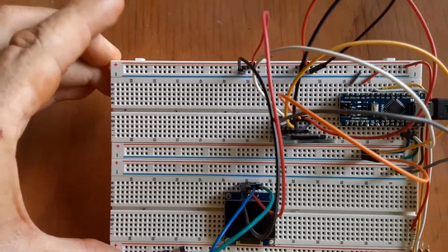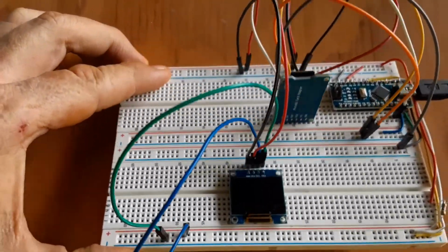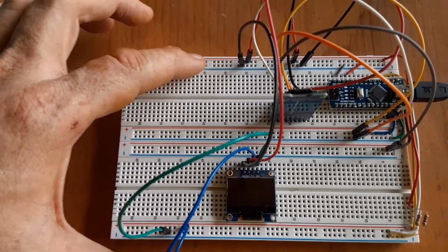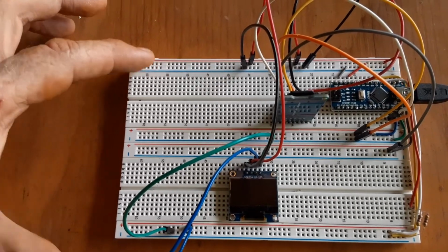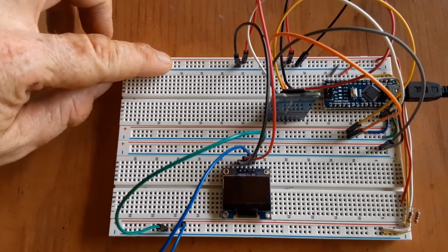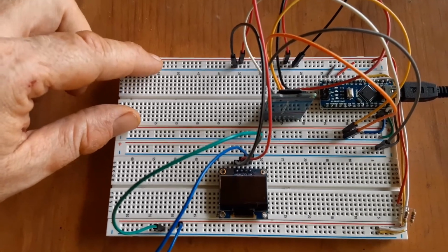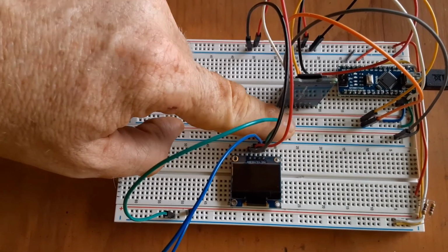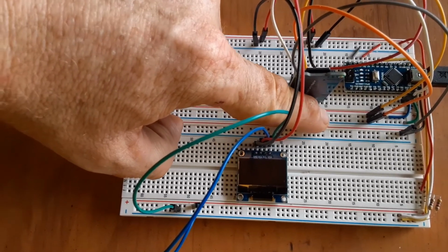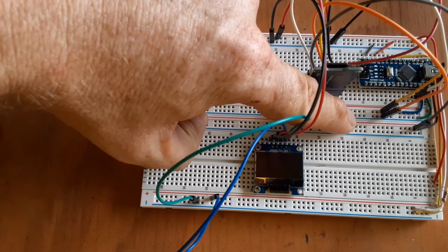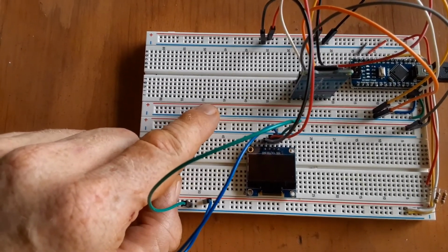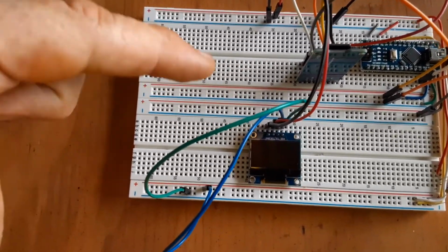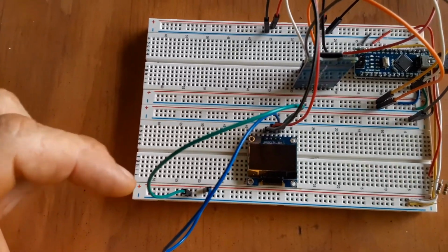And this is a typical setup I have to work with these. Most breadboards typically have little knobs on one side and holes on the other, so they link together and you get a nice big spot to work with, and more of these rails or buses going down the side. So up here, I've got power and ground, lots of places to get power to things. And then down the middle here, where the connections are made, I always keep the SPI communication, so that I have a MOSI rail, a MISO rail, and a clock rail, and then I can hook up lots of SPI devices. Lots and lots of places to hook those up.